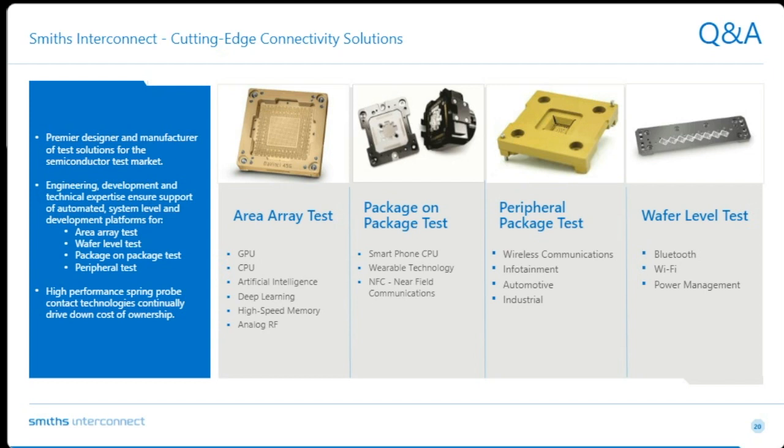We don't have Da Vinci elastomer sockets. I think the vertical probe solution is a better solution. It's better suited for high volume tests or lots of test cycles, and certainly for larger packages. We're seeing so many large GPU and CPU packages that we generally focus on the vertical probe Da Vinci coax solution as opposed to an elastomeric.